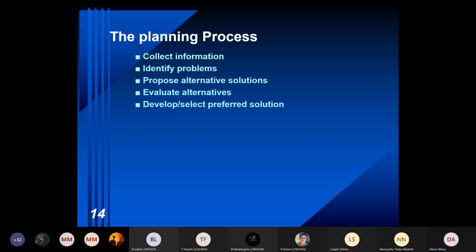So you then need to go and collect some information pertaining to that intersection. Look at the past vehicles in the different approaches, right turning, look at the signalization of that intersection. There's various information you can collect. You can sit at that intersection and do an observation, a vehicle count, right?